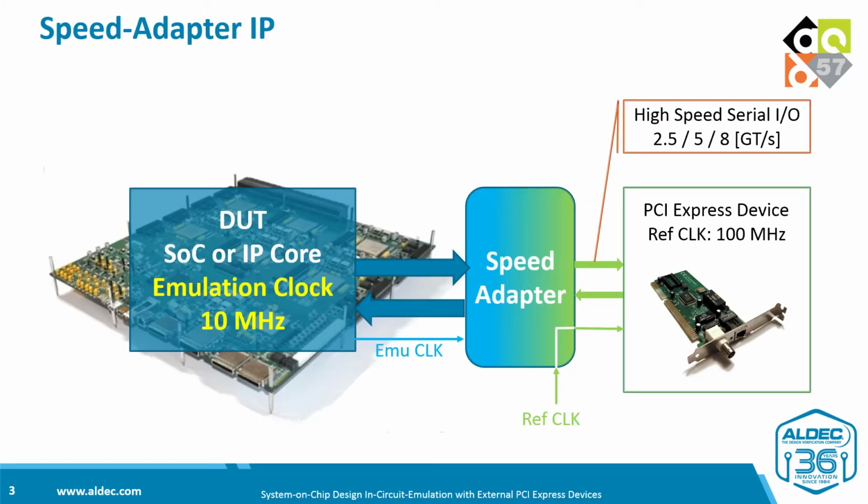As it was already mentioned, connecting external device with emulated design requires using a speed adapter block. I think that analyzing the PCI Express speed adapter application would be interesting for many because a growing number of application-specific SoC designs adopt the PCIe interface as a common interconnect with other devices that are readily available on the market.